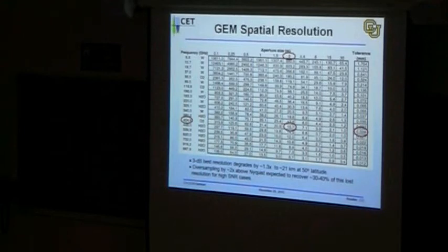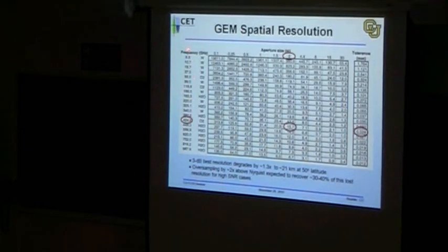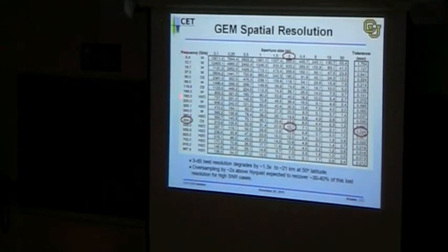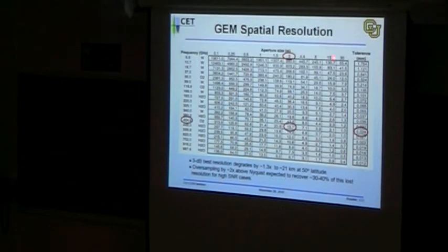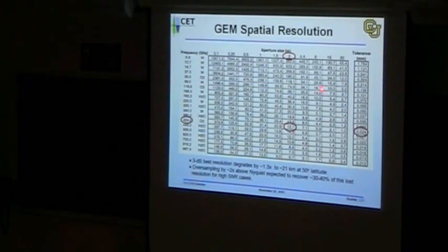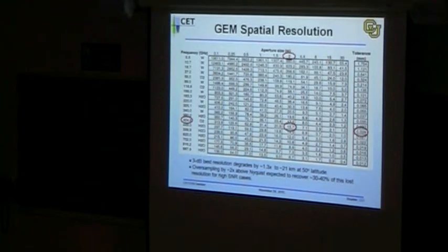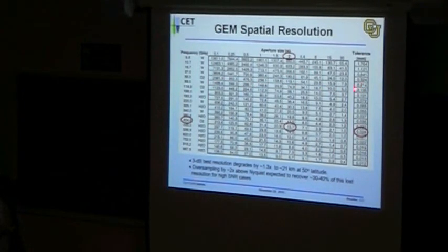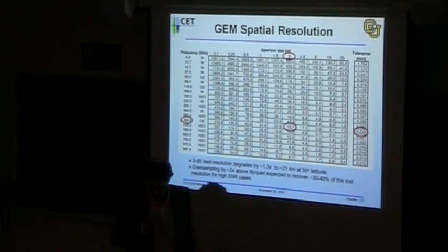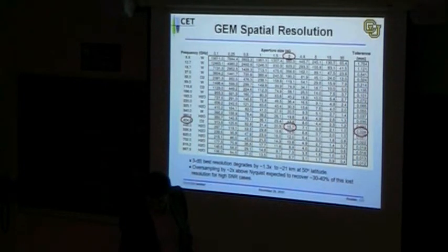It was first explored back in the late 1970s. Once we observed the Earth from low Earth orbit with microwave, immediately the obvious thing was to try to put it in geo. Well, if you do the calculation, and if you want to go to geostationary orbit at any of these various frequencies that we typically work at, all these have their various advantages and disadvantages. And if you want to have a certain spatial resolution, which is in this matrix, then you've got to have a certain antenna size. And you can see what happens immediately. If we want to observe, for example, at 89 gigahertz, and we want a spatial resolution of 10 kilometers, 15 meters is the antenna size. Now that's a pretty big antenna, especially recognizing that that antenna has to have a surface tolerance for it to operate of about 100 microns. So building that kind of a structure is extremely expensive, and it is really what's kept us from putting microwave in geostationary orbit since it was first conceived.